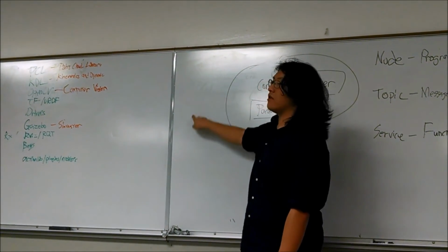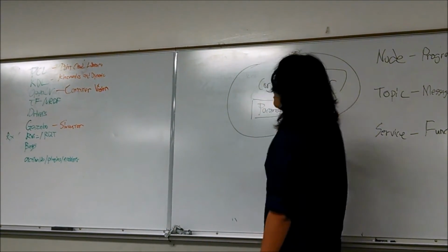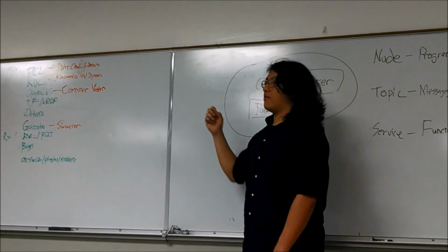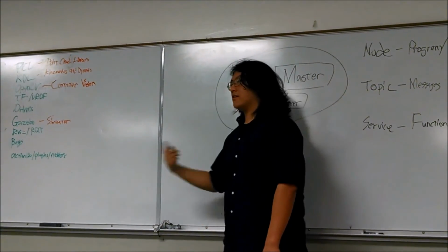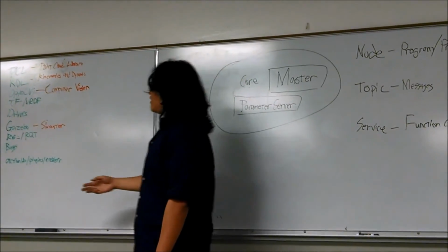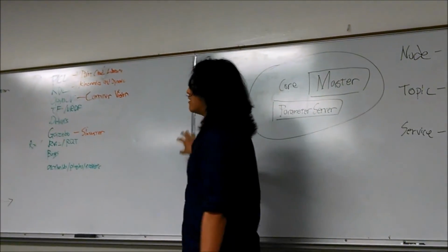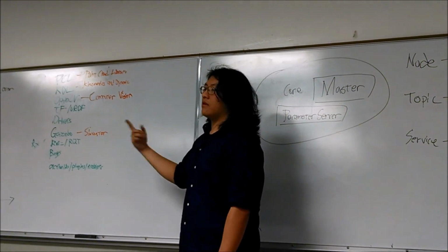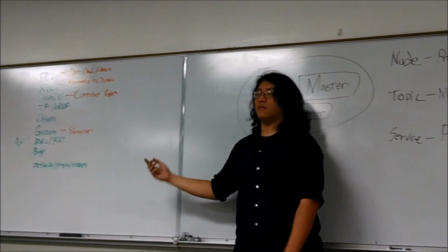Between each of these nodes, because they're different processes, ROS is going to have to serialize the data and then send it over a TCP pipe and deserialize it on the other end. And this leads to a whole lot of overhead. Rather, you can have each of these nodes be nodelets, and they can pass a single pointer between each of them and just look at the same memory, making it much faster.